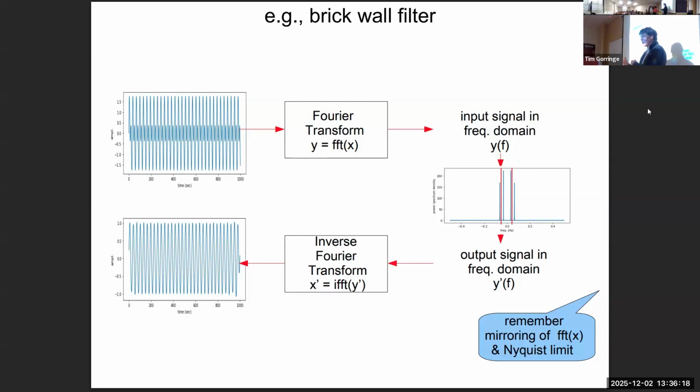they're relatively closely spaced in terms of what we've been able to achieve with low pass RC filters and Hamming rolling average. So we're going to start with a signal that has two frequencies in it. We're going to Fourier transform it, and that time domain signal will become, in blue here, this frequency domain signal. It's a little hard to see, but I haven't removed the mirroring here. There's two spikes on the left of the origin, two spikes on the right of the origin. These are the two different frequencies, which is mirrored.